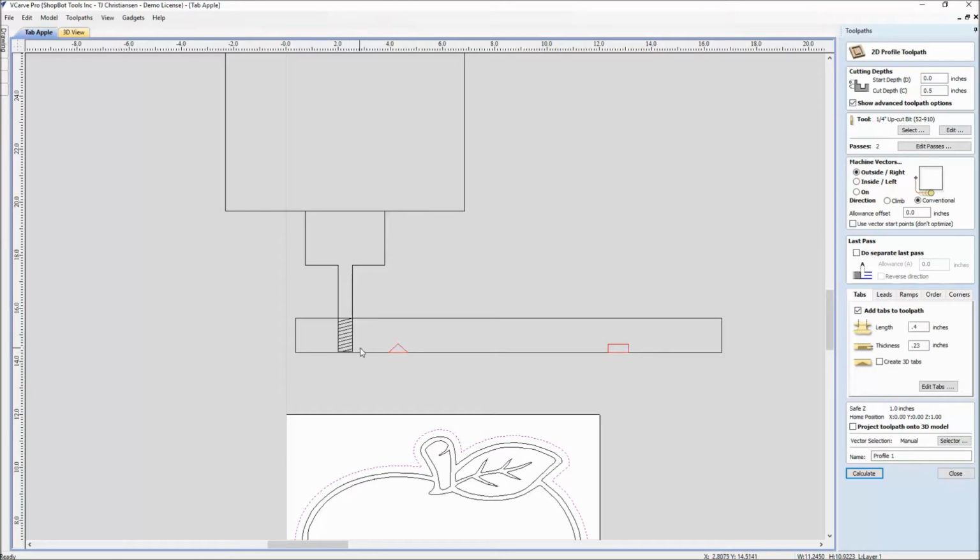When the machine is going along making its profile pass, the machine just has to ramp up and ramp down in the Z and continue on going. Where when you have the 2D tab, you actually have the machine stopping, pulling up, stopping, and going over, again stopping, going down before it finally finishes. So you can leave a little bit more of an edge from the machining on a 2D tab. However, a 2D tab is again bulkier and gives you a better hold down. So on parts like aluminum and plastic where you want to have a meatier tab, sometimes the 2D. So we'll talk about this towards the end of the tutorial, the different tab sizes and shapes for the material that you're cutting.